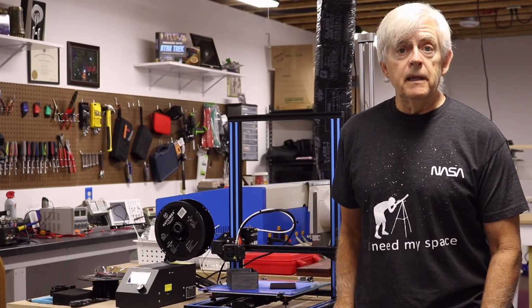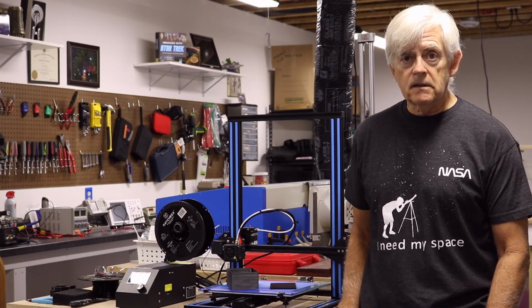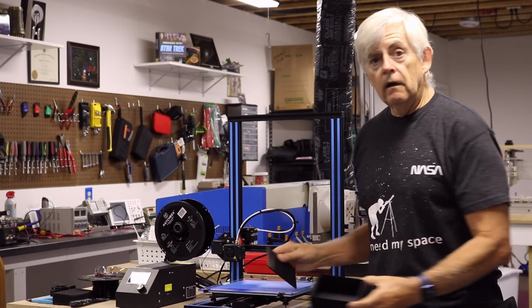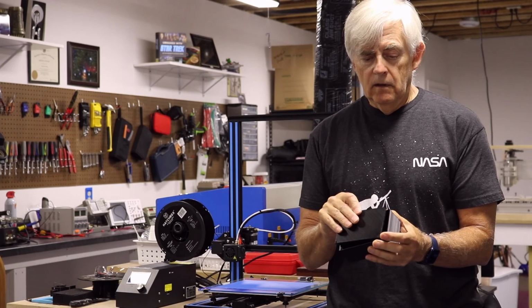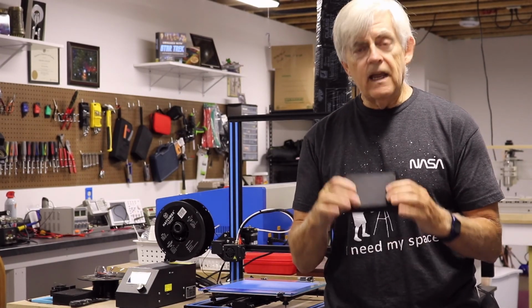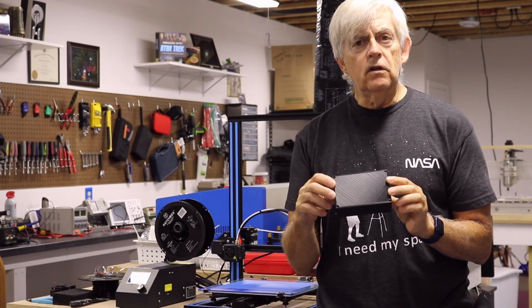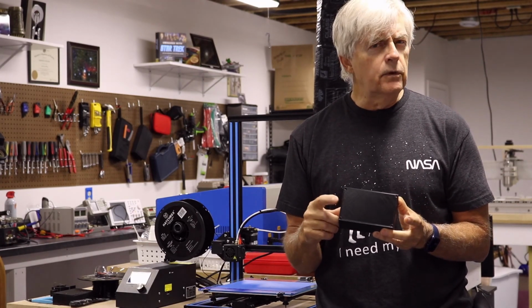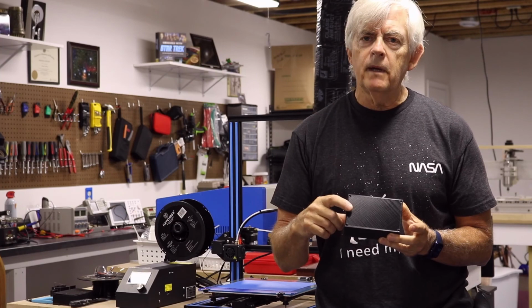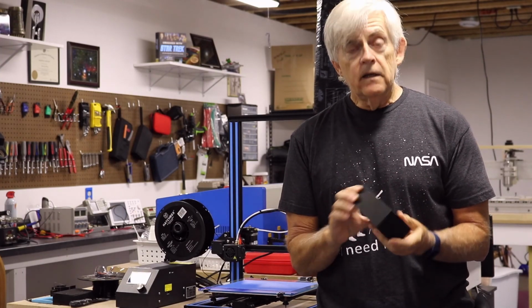Okay, our 3D printer has finished doing its job. We printed the lid and the utility box, and the files from Cura work just fine. It snaps together just as it should, and that is why it's important to allow that little bit of clearance. So when you design things, always keep in mind, never make them size on size.